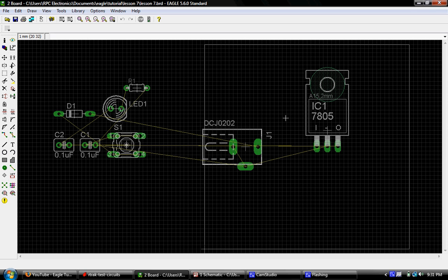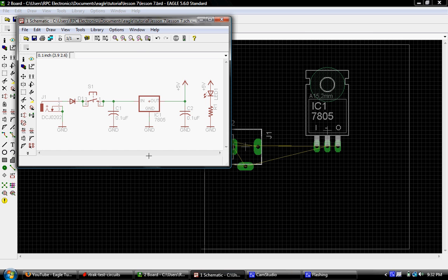There is an easy way of identifying them visually, and by demonstrating this, I'll give it a chance to show you something. In lesson 6, I'd said something along the lines of the power connector was connected to the left pin of the voltage regulator, and that is true. The only thing I left out is a caveat: we have a protection diode in between these two, and you can actually see the air wire here jumping from this pad all the way over to this diode. But if you weren't sure, there is a way.